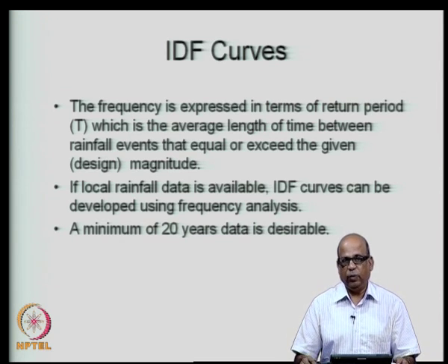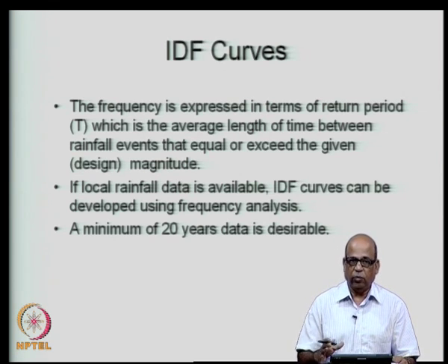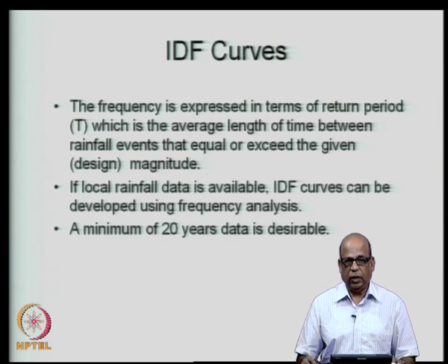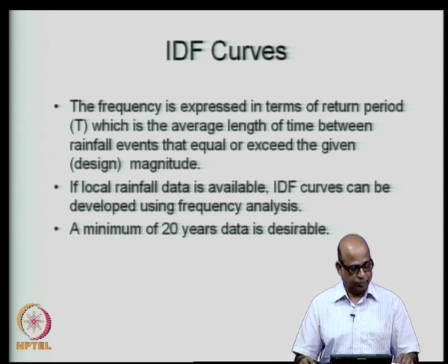Typically, a minimum of 20 years of data is desirable for constructing IDF relationships. If you have less than 20 years, then it may become rather biased, statistically biased, and therefore, a reasonable length of data is necessary for construction of the IDF relationships.